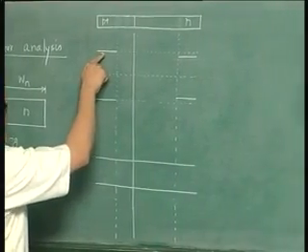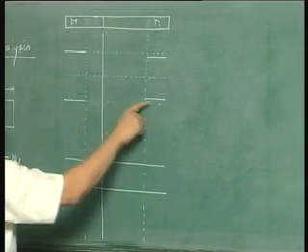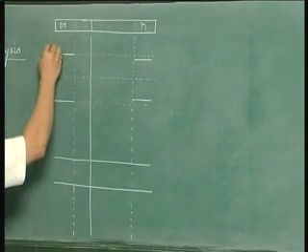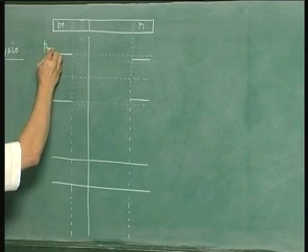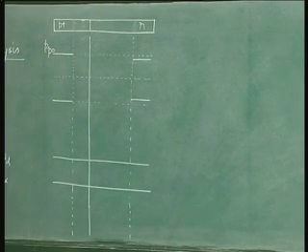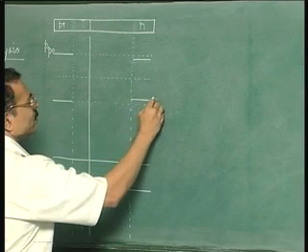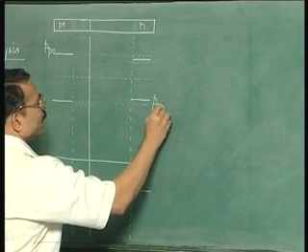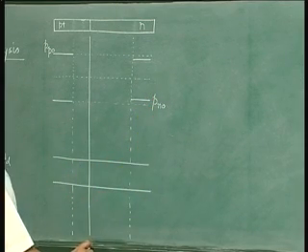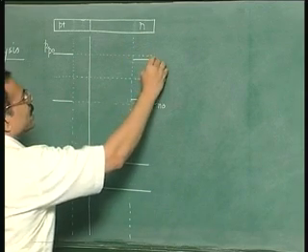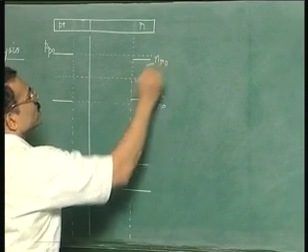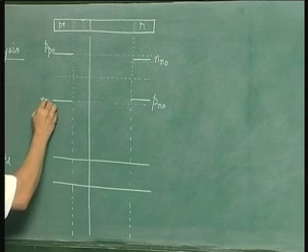The concentration of holes will be more on the P side than the N side. Okay? So let us call this as Pp. And since we are considering equilibrium conditions, this is Pp0, and this will be similarly Pn0. Analogously, this is the concentration of electrons on the N side, so this is Nn0 and this is Np0.